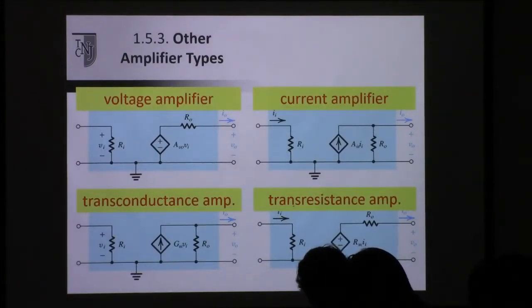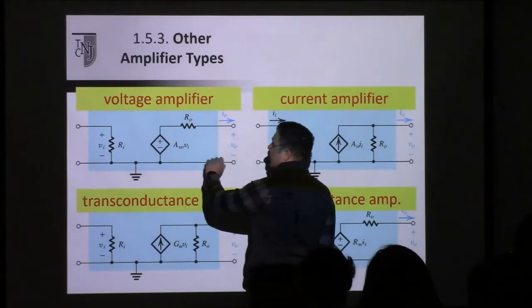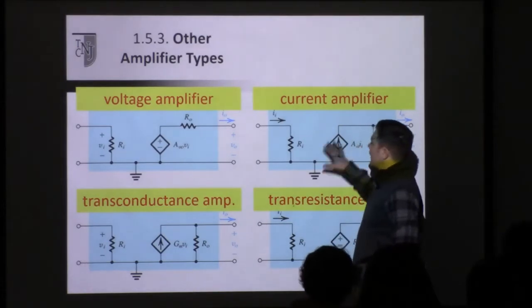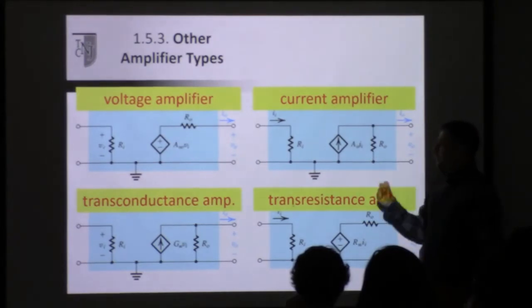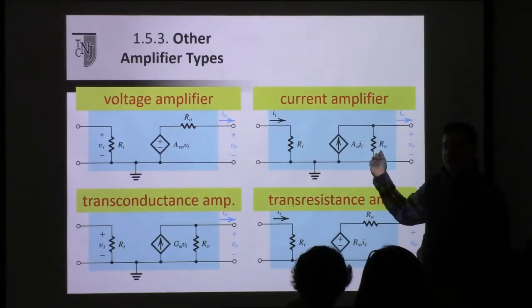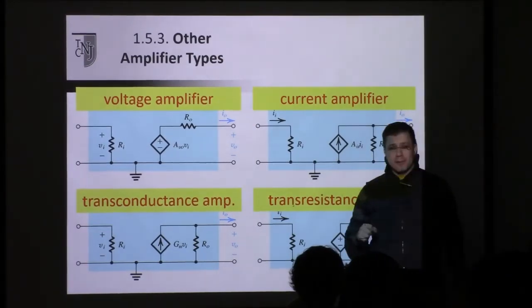Okay, so then this is sort of where we left off. We touched upon it, but I'd like to maybe start fresh from here. So the four different basic amplifier types. These are four basic ways of representing an amplifier. We've so far mostly been addressing the voltage amplifier, which has an input voltage and output voltage. We also have a current amplifier, which measures current at the input and generates an output current. The main difference going from here to here is that now our output is configured as a Norton type source as opposed to a Thevenin.